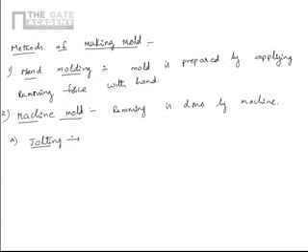The disadvantage is that the top of the molding sand will be loose, so we get non-uniform ramming, with good ramming only at the bottom. This is a problem here. This is the mold box where you see the cavity. This is the molding sand.